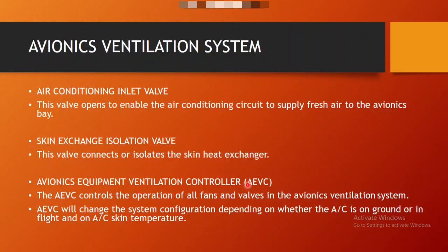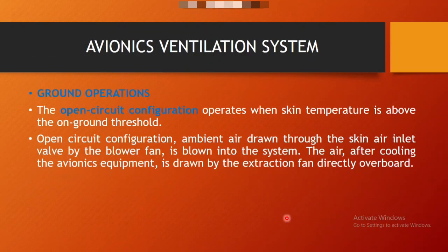Avionics equipment ventilation computer. The AEVC controls the operation of all fans and valves in the avionics ventilation system. The AEVC changes the system configuration depending on whether the aircraft is on ground or in flight, and the aircraft skin temperature. Regarding skin temperature, I have already uploaded a video on my YouTube channel. You can search on my channel. So now this is the main part of the avionics equipment ventilation system.